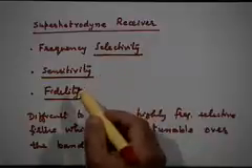Now, if you have all these ingredients in the RF amplifier, you are bound to most probably generate an oscillator rather than an amplifier when you try to realize it, because these are the prescriptions of an unstable amplifier. High gain associated with high frequency selectivity will typically generate conditions which will be very difficult to control. Your parasitic capacitances and various other elements in the circuit will make it highly unstable. It will be very difficult to realize such a tuned filter which provides you all these things.